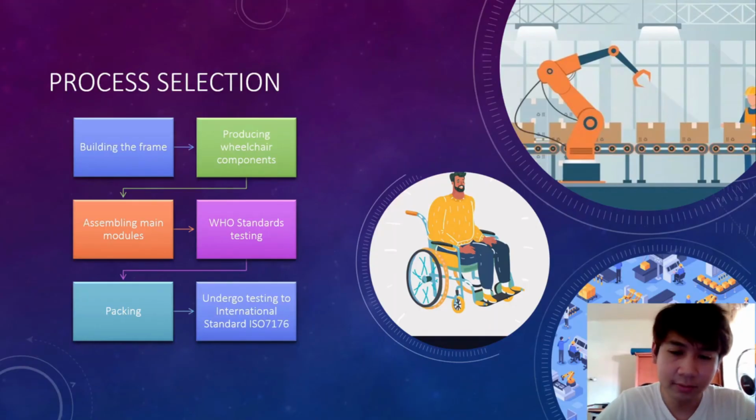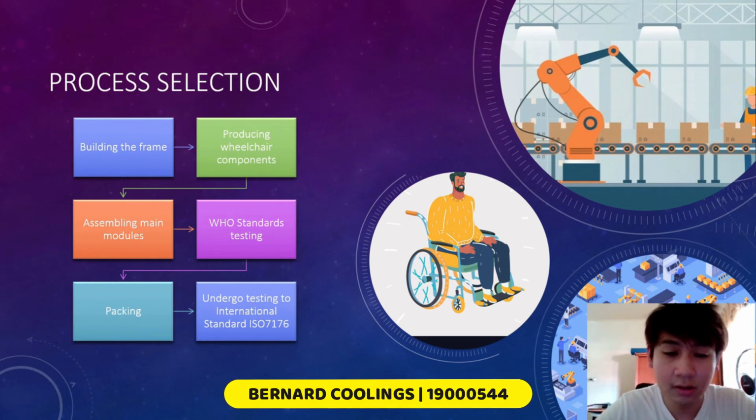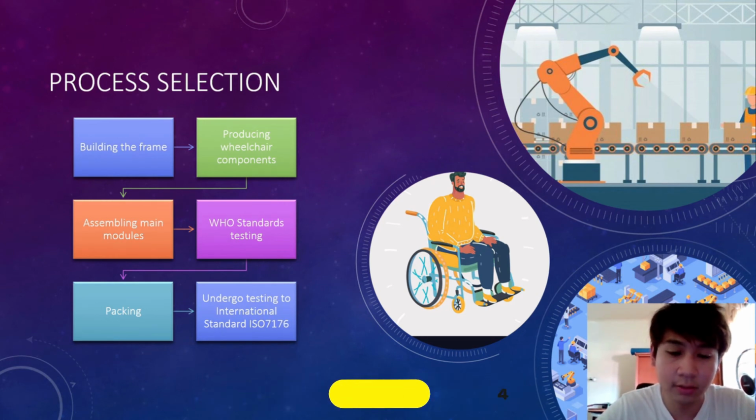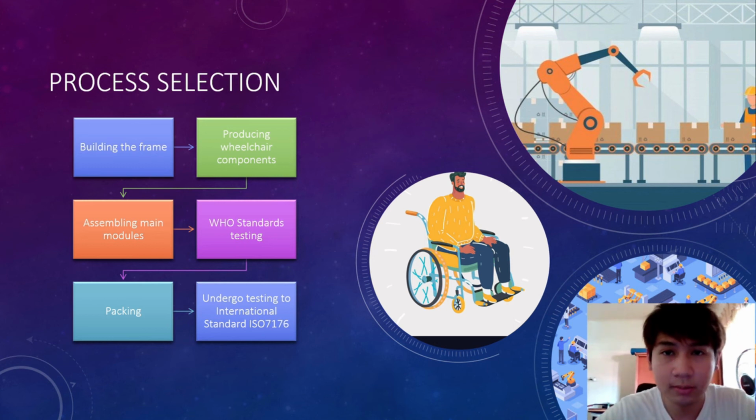For the manufacturing process, we begin with the frame building. It involves the machining of the wheelchair frame parts and components into precise measurements. For example, sheet aluminum parts for the handle assemblies are cut and shaped in a special purpose booth, after which cut and bend components are transferred to a location within a workshop complex for assembling into sub-units.